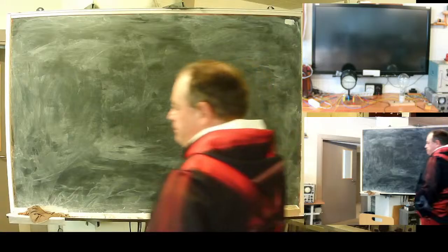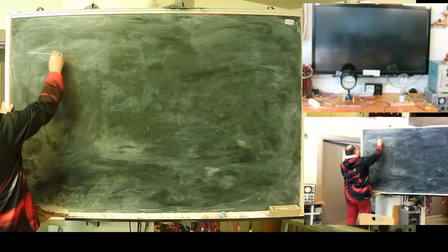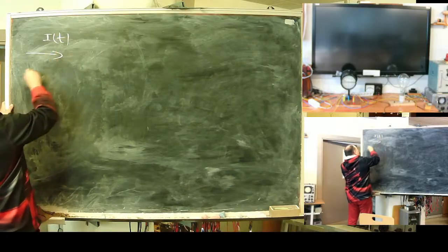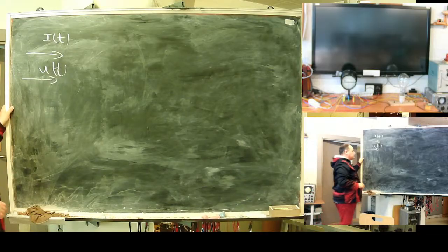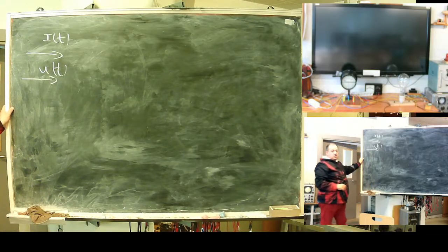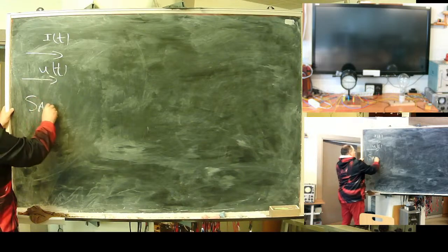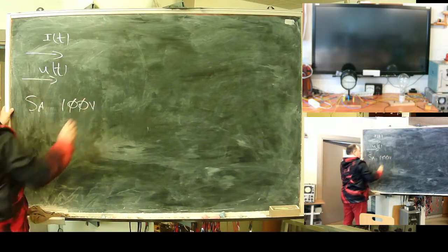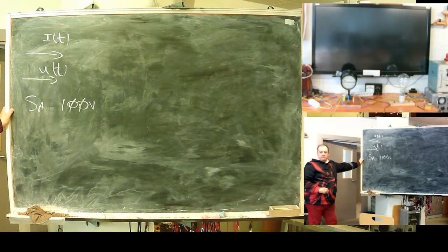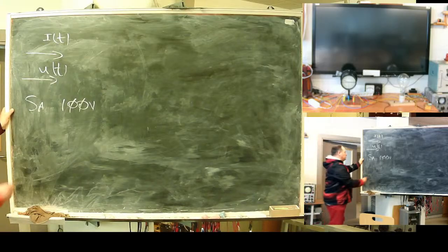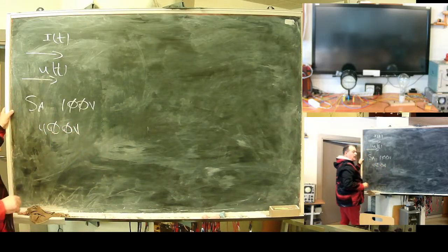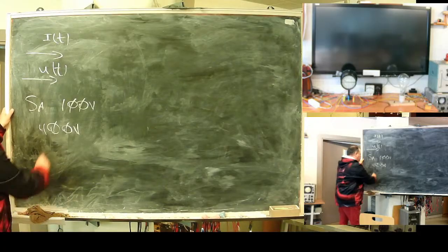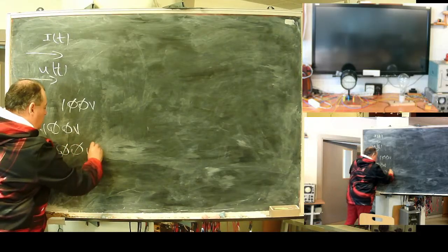Input circuit. So we may have currents, we may have voltages. They are at levels, if it's secondary circuits of a substation, 5 amps, 100 volts. If we monitor, for example, a solar system, it may be 400 volts and so on, and on the DC side up to 120 volts.